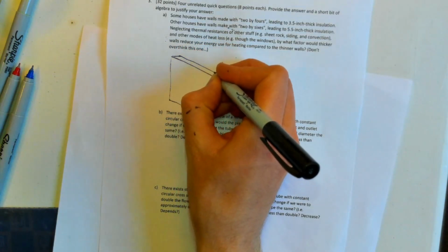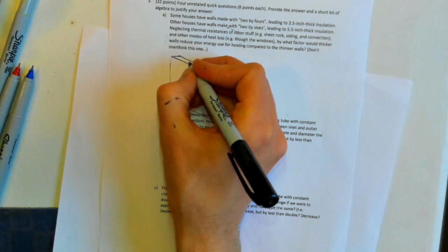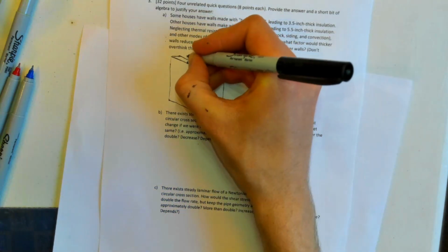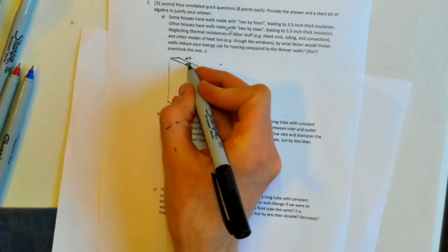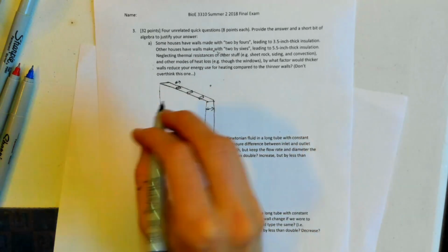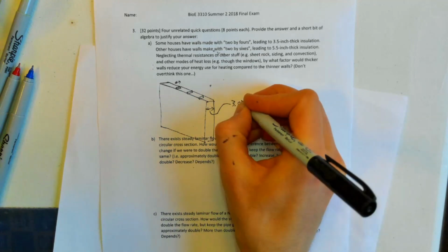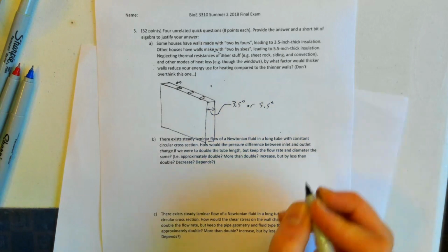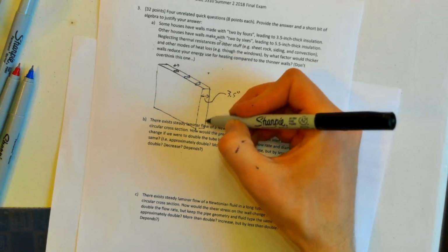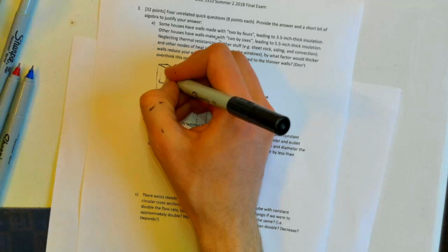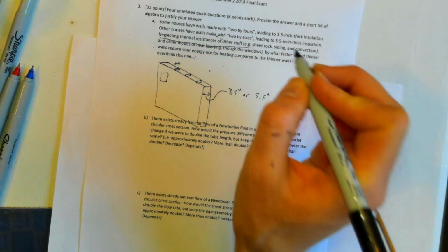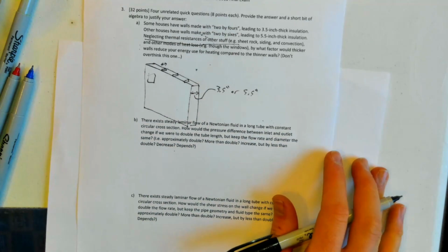So I'm looking at the wall of my house. Whether it's 2x4s or 2x6s is basically saying how thick are these boards right here, essentially dictating how thick is my wall right here. So this thickness could be either 3.5 inches or 5.5 inches. And in addition to the insulation in my walls, there's also sheetrock on the inside and siding on the outside. Strictly speaking, these walls have windows in them, which provide a different path for the heat to flow through. But I'm saying neglect all those thermal resistances of all the other stuff. Let's just consider how wall thickness affects it.